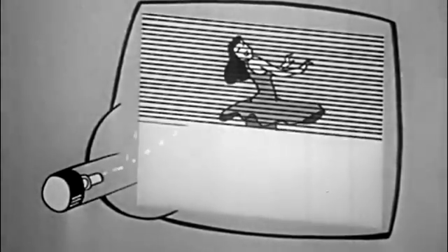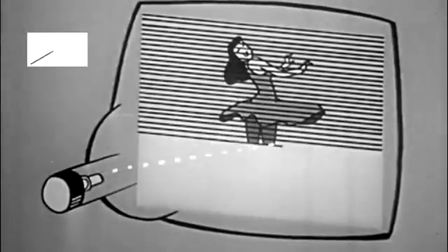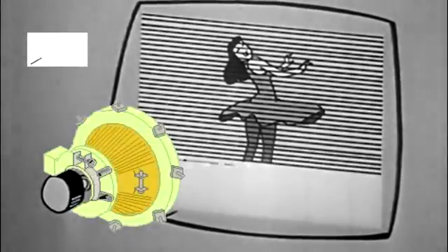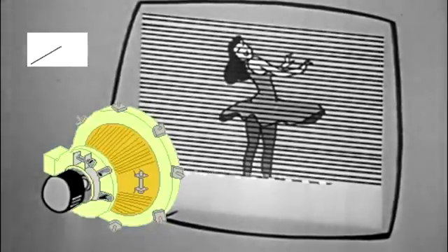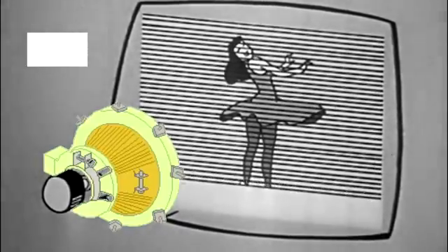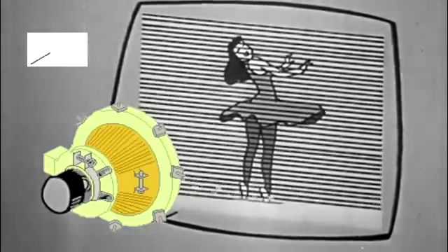The CRT had to then move the electron beam around to recreate the original picture frame. This was done using two coils of wire around the neck of the CRT. The camera has to tell the monitor where there is a dark or light portion of a picture. But it also has to tell the monitor when to start and stop producing each line of video, and also when to begin and end each field as well. That's the purpose of synchronizing signals. A group of special signals are sent by the camera to pass along this synchronizing information.